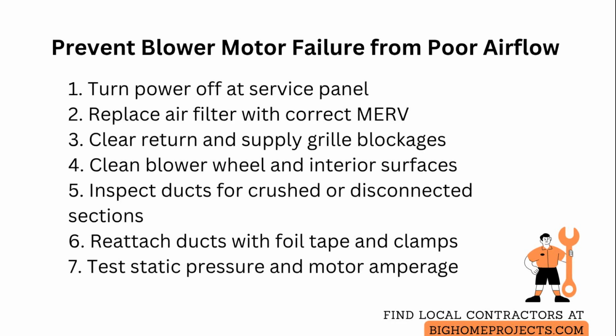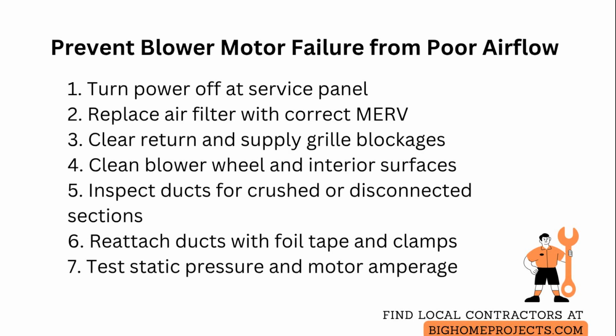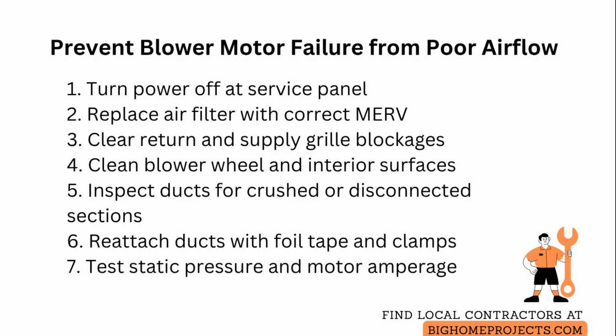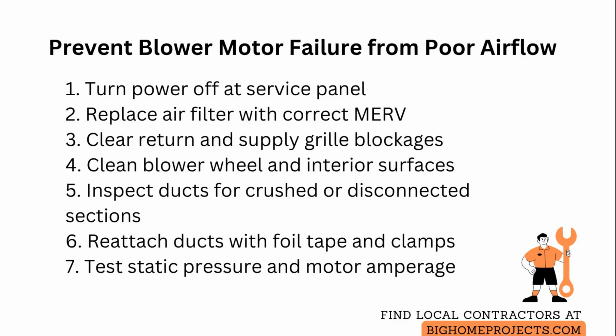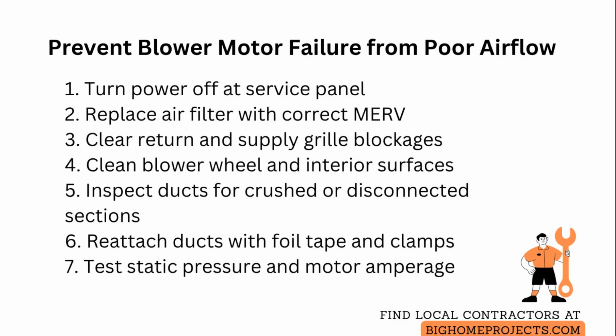Look for crushed flexible duct, disconnected sections, or large nests, and remove obstructions or reattach ducts with foil tape and approved clamps. If the motor still overheats after cleaning and duct repairs, measure airflow or hire a technician to test static pressure and motor amperage to confirm whether the motor is damaged or operating outside the original specifications.